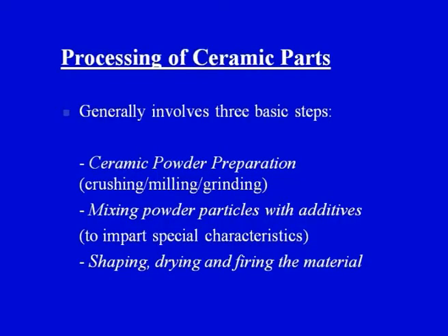Once this raw material now is ready with us, we will just give it a particular shape for which we are making the ceramic product. Now depending upon the requirement, suppose we want to make a flower vase out of this raw material, we will give it the shape of a flower vase. So next stage or the third stage is shaping. So we can give a shape to the raw material using any of the techniques like pressing, slip casting, extrusion or injection molding, and there can be other processes also, like jiggering, which we have not covered, but there are a number of processes which can be used to give shape to the ceramic raw materials.